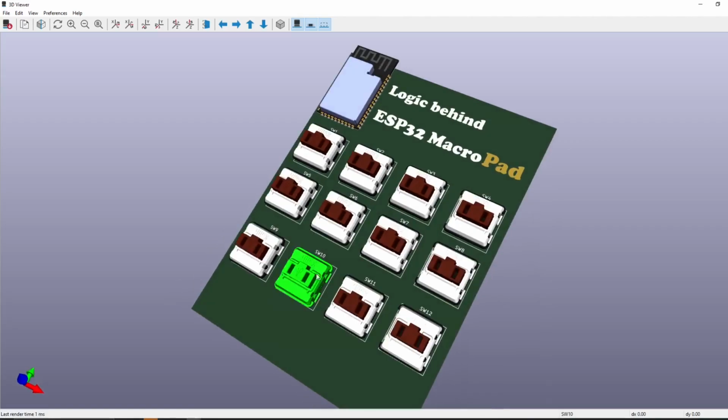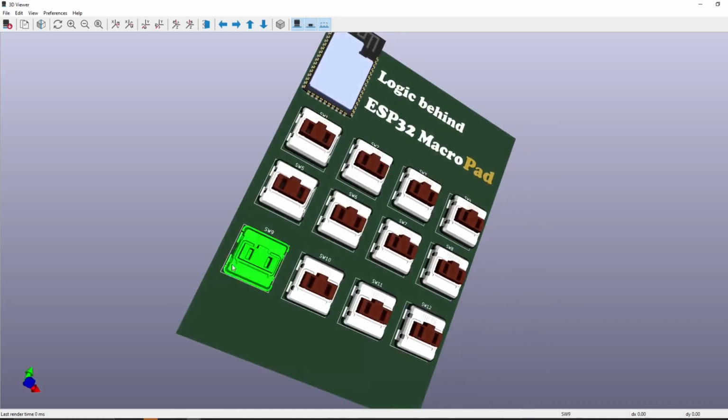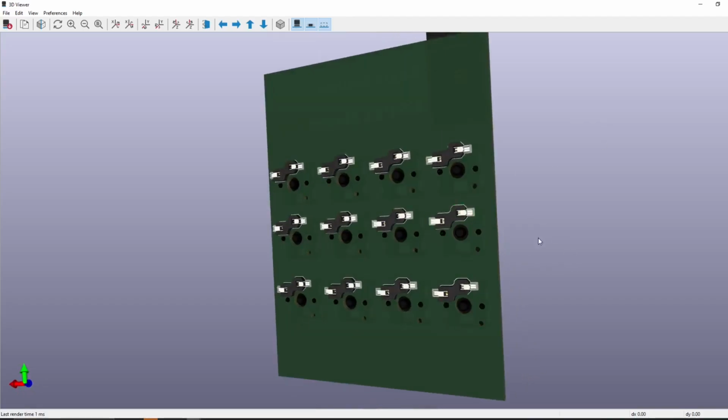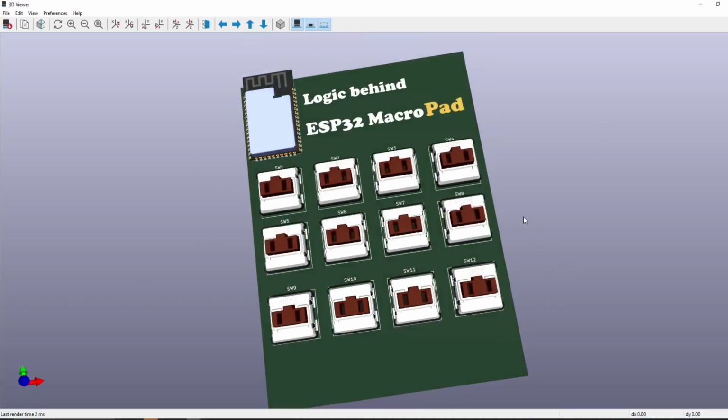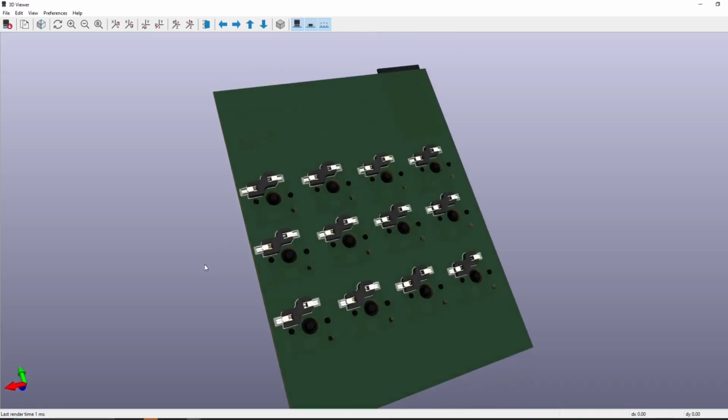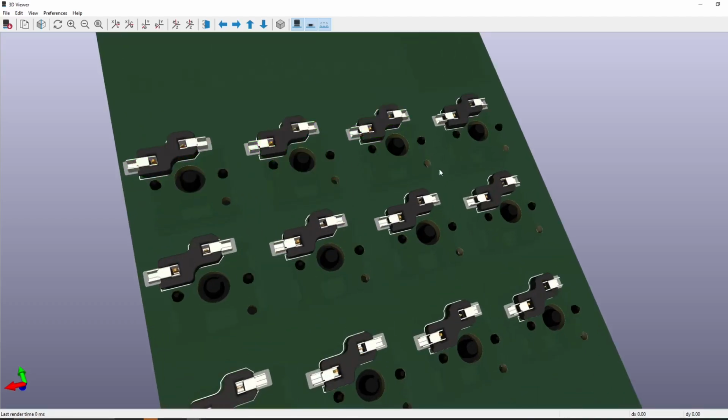I know that this is maybe now too complex, and that will increase the cost of your board, but I didn't see anyone else doing some harder debouncing for the macropad, and I decided to try this. This will maybe be stupid because our microcontrollers became much faster, so they can process this and the other functionality, but let's try maybe outsourcing the debouncing to the hardware.